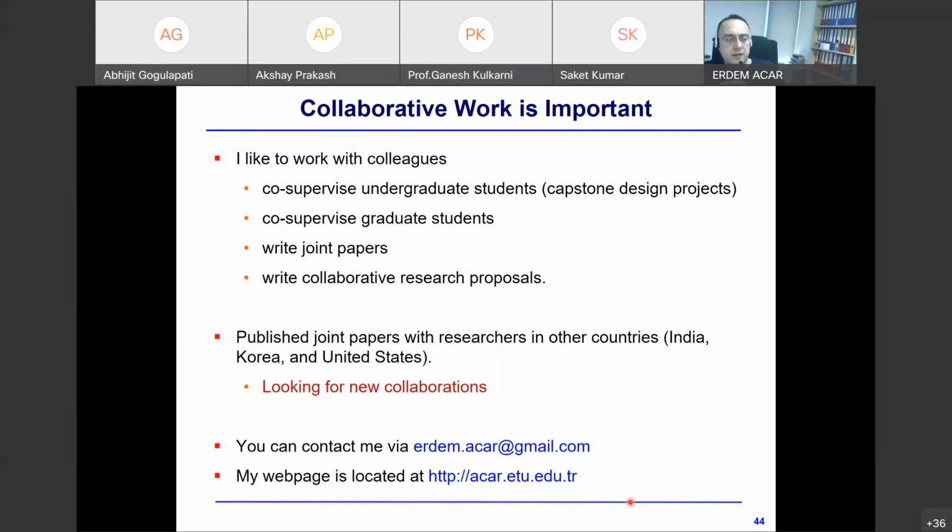And then you can improve the accuracy of your surrogate model with some adaptive sampling techniques. That is, you start with an LHS design, 10 times the number of variables, and then you construct your surrogate model. And then adaptively, you can add more points near the locations where you want to improve the accuracy of the model. So I have used surrogate with LHS and EGO.